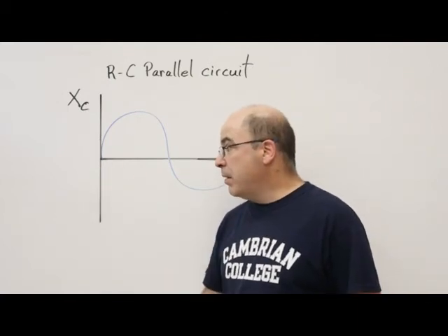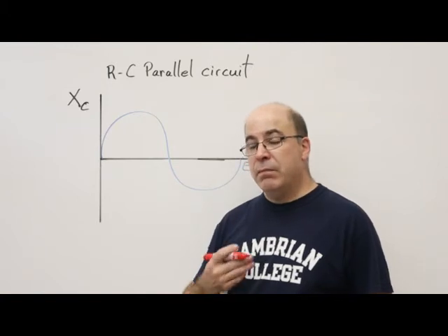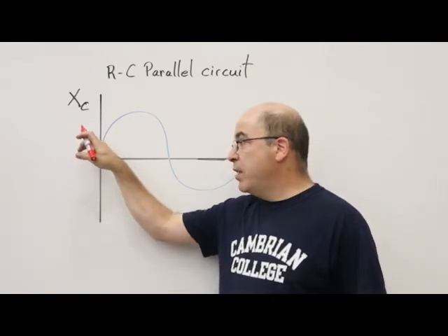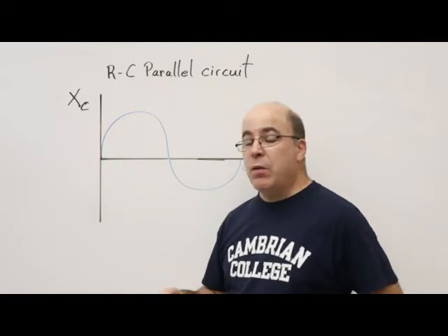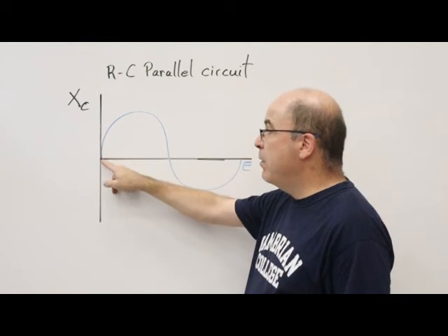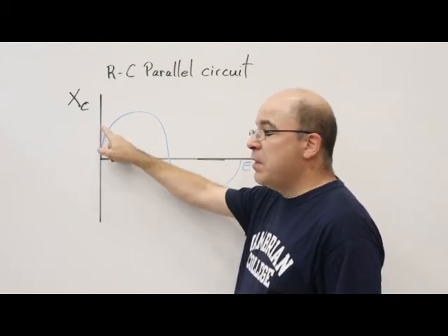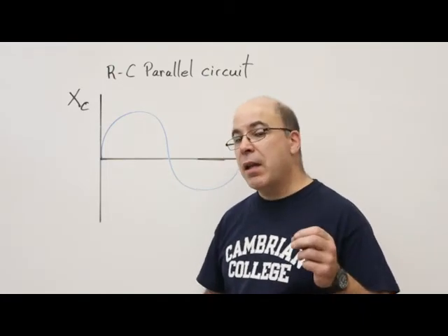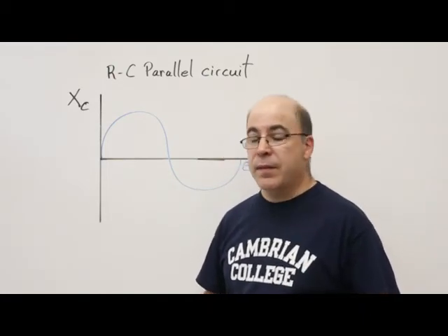In this case, if I was to use that logic, that means that my current is actually going to be at a higher value where I'm at the 0 point with my sine wave for the voltage. Current's going to start up here in the positive alternation, and there is a 90-degree phase angle difference.